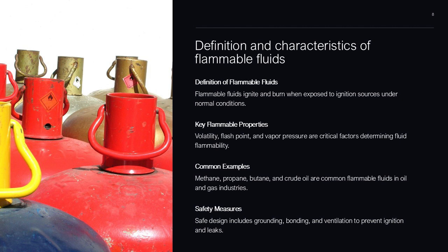These fluids are often stored and transported under pressure, which increases the risk of leaks and vapor formation. Ignition sources such as static electricity, hot surfaces, or open flames can trigger fires or explosions. Understanding these properties is crucial for designing safe systems and implementing preventive measures like grounding, bonding, and proper ventilation.